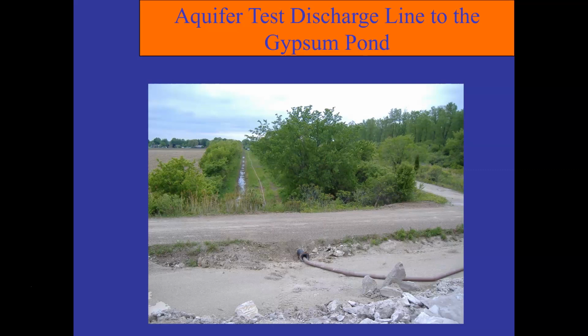Typically I like to have part per million levels, maybe up to 50 parts per million. You can see it down to, I think, about 100 parts per billion. You can see a little bit of the tracer. So when you're in the part per million level, it is visible. That's nice. I like it to be visible, but it also has to be treated. So you've got to make sure the carbon will treat it.